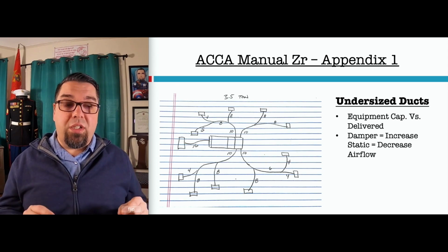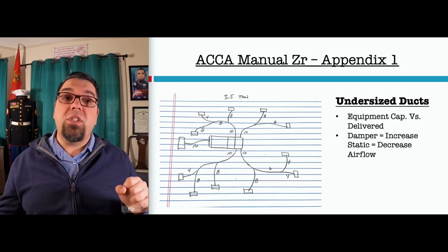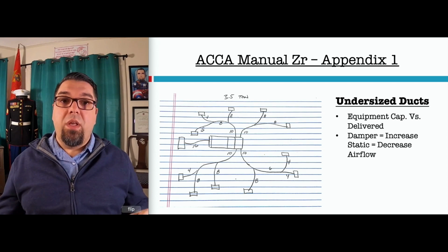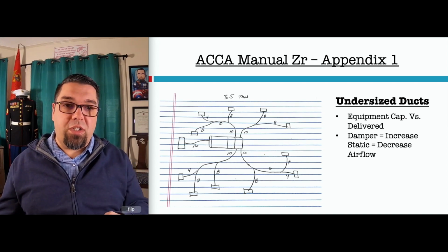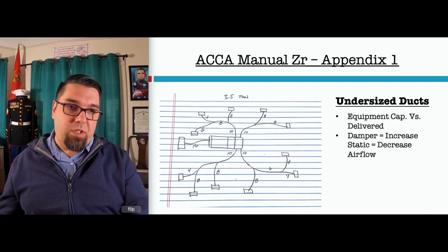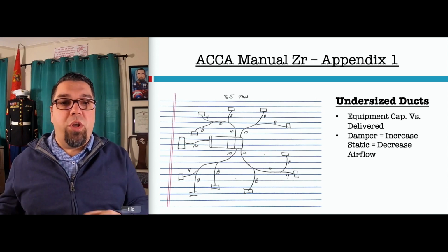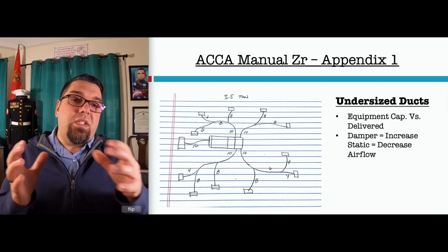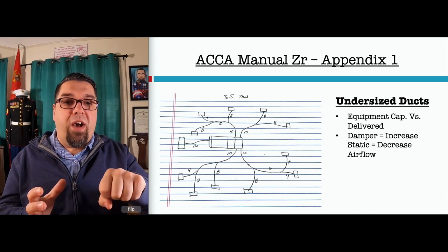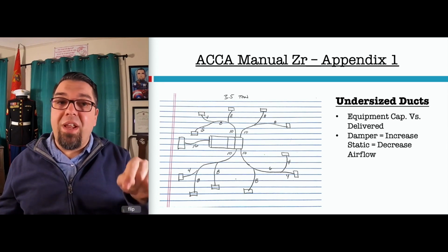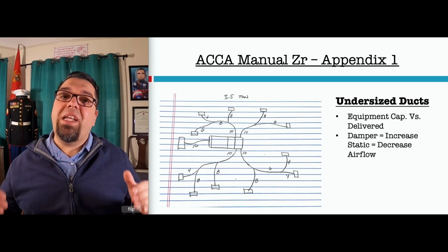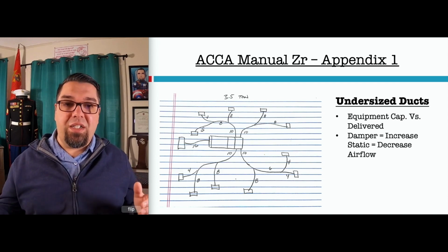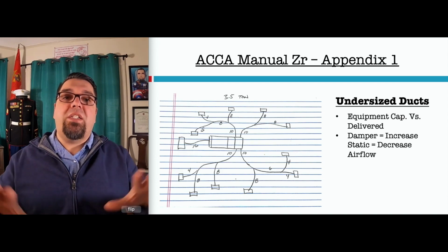What you do need to do is make sure that you install dampers, all right, at each takeoff by the trunk, because you're doing trunk and branch systems. We're not doing flex monsters, right? What that will do is when you increase the static pressure, you'll be able to modify it. Just putting a damper in is not going to fix an airflow problem. By dampering and zoning pieces of the duct system, all right, it's not going to fix a comfort issue elsewhere.